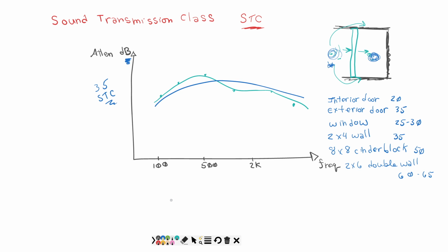We're going to take a closer look at this in a future video, but I'll just do this real quick. So I'm looking down on the wall. So this would be the plate. And the studs are coming up at you. All right, so these little X's, these are the studs. I'm just going to put 3 framing studs coming up. So normally you would just have this and you'd have one layer of drywall on the inside, maybe a plywood or a composite on the outside.